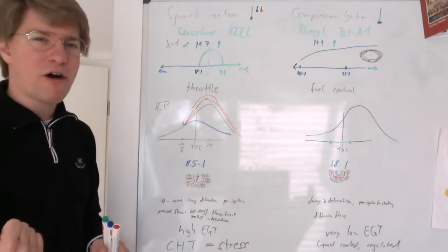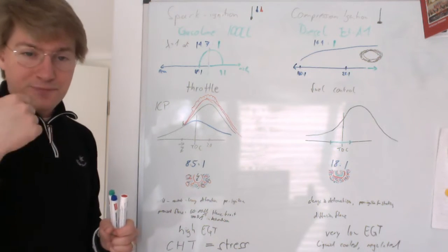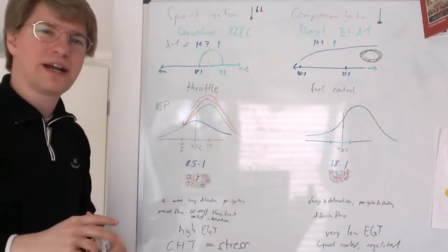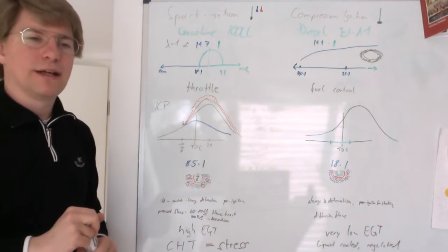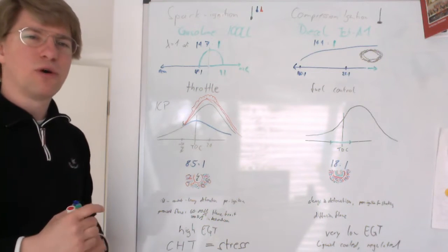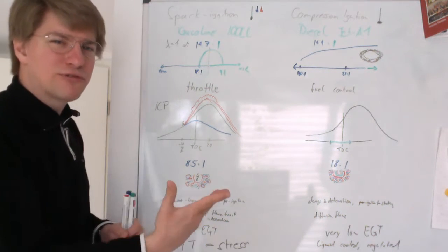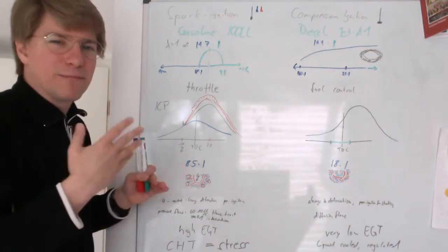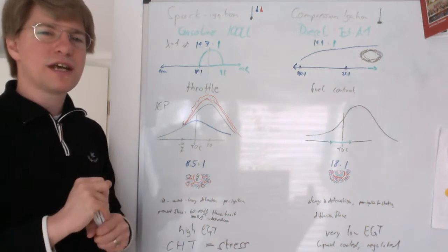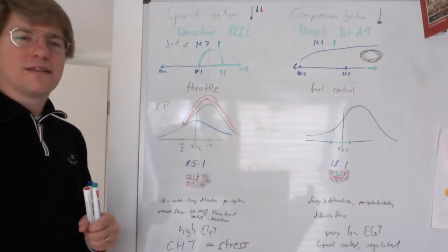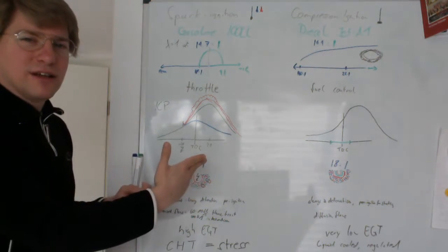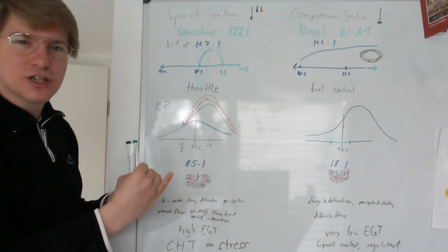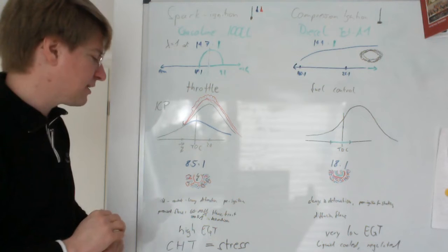So pre-ignition can be caused by faulty spark plugs that cannot conduct the heat away from the spark plug into the cylinder head, or by deposits in the cylinder that get too hot. And usually to trigger pre-ignition, you need to be in detonation first. But people seem to confuse pre-ignition and detonation often. And the difference is detonation happens after the spark plug fired, and the definition of pre-ignition is it happens before the spark plug even fires.